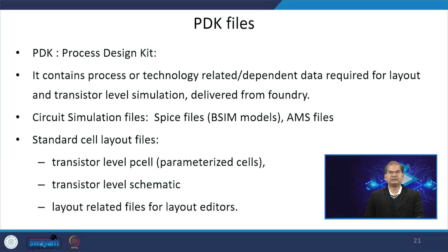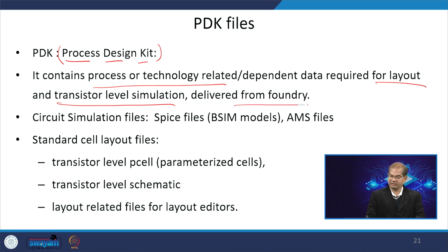Now, we will look into what are the files provided with the process design kit. The PDK stands for process design kit. It contains a lot of files. So, here it summarizes what are the files there inside a PDK. It contains process and technology related files and data required for the layout and transistor level simulation. Those are provided by the foundry.